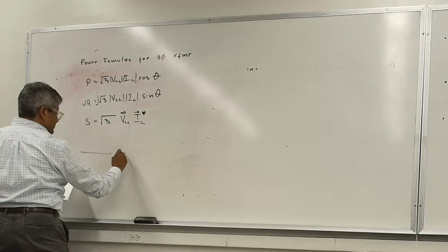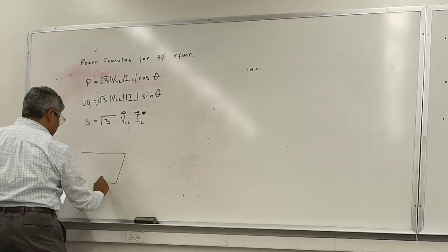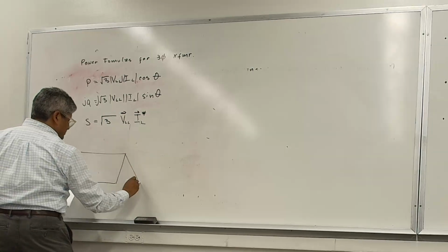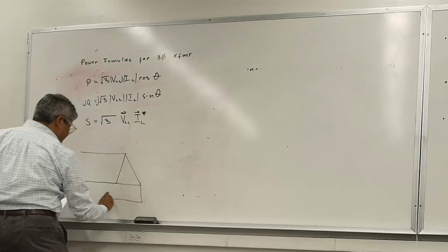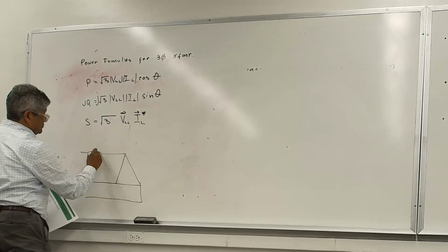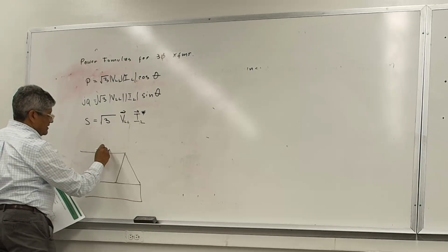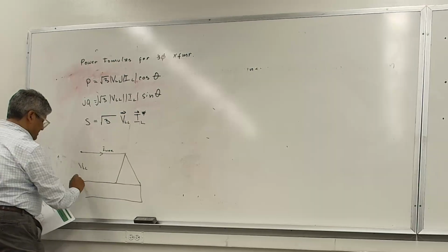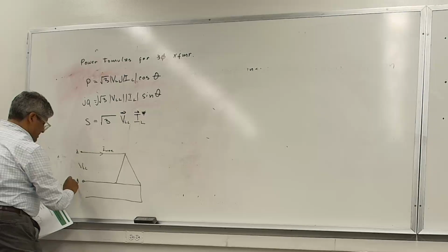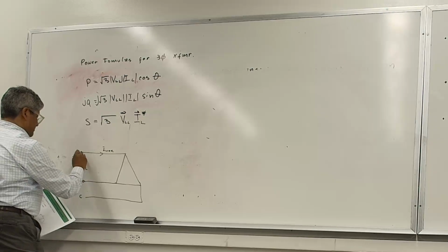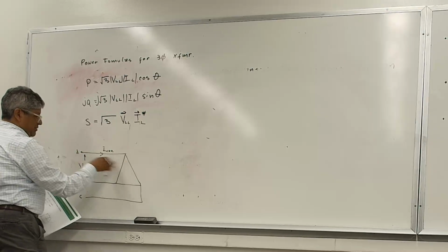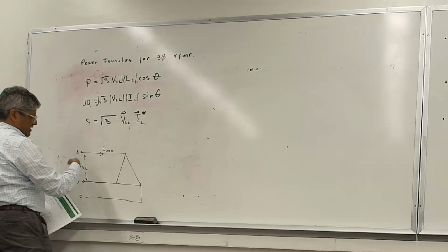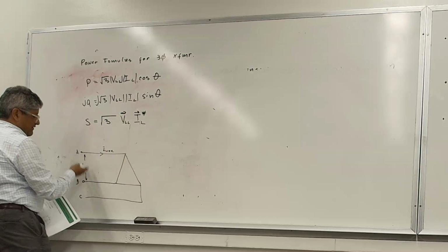So, for instance, if you were to have a delta on one side of the transformer, I'm going to call this the primary, as a delta, this is what we call the I line. This is the voltage line-to-line from A, B to C. So that's what we call line-to-line. And we talked about this before, where in this case there is no neutral, right? So we only have line-to-line.